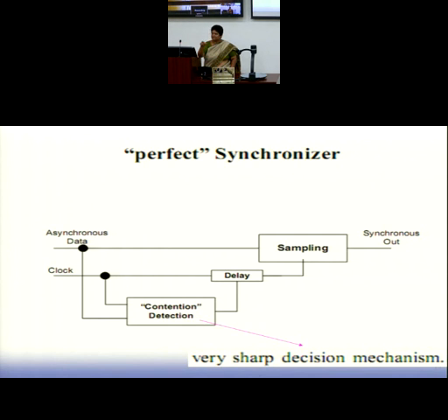If I am giving it 1 extra cycle, then within that I am allowing it to resolve, or even not in that one cycle, the moment it arrives, I understand that it is metastable, I immediately start providing help to it, so that by the time the clock edge comes, the data is resolved and I am able to latch it onto the system. So you need to now provide an aid. Because we want a one clock cycle solution, there is a design overhead. So we need to actually start designing for one clock cycle solutions.